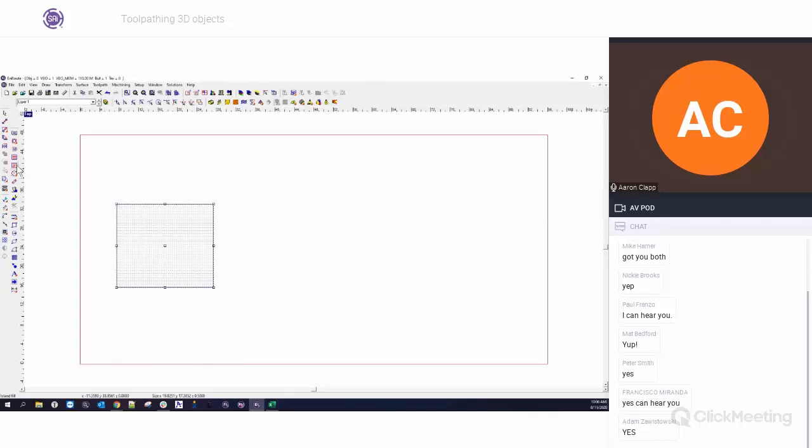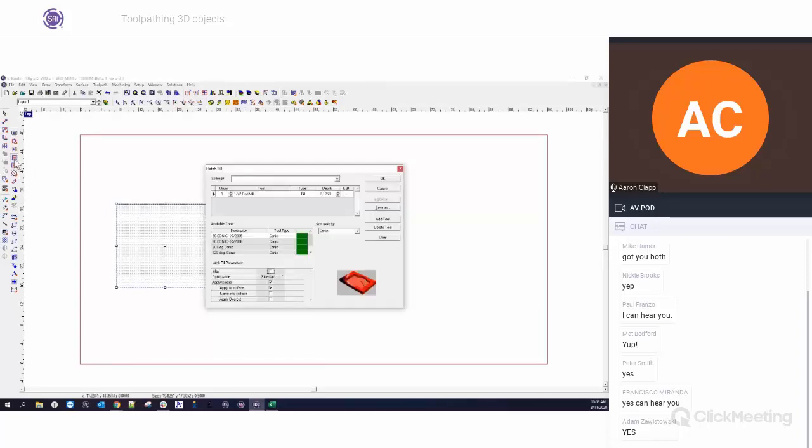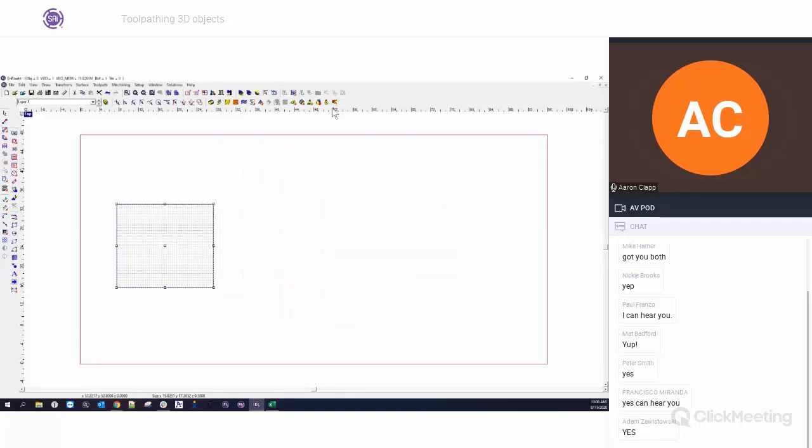In this case, we're just cutting out a flat piece. Honestly, I'm just going to stick with the hatch fill. It goes back and forth, and it's very efficient. And what I can do is tailor my path to match what I think is probably best with the flow. So for example, my flow kind of tapers, or it's kind of flowing from left to right. So I'm going to try and make my toolpath go from left to right as much as I can.